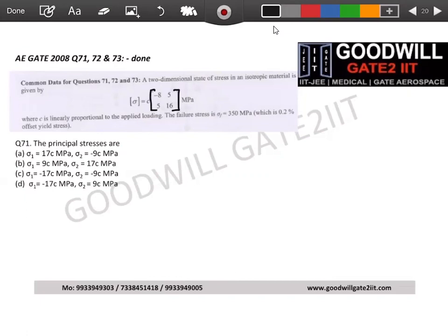If you have a stress matrix, its eigenvalues will be represented as principal stresses. So principal stresses of a stress matrix, if you use this application in maths, any matrix's eigenvalues are nothing but principal stresses in our case. What I'm trying to tell you is, in maths, you simply say you have a matrix, please calculate eigenvalues, fine. But now in structures, if that matrix is a stress matrix, its eigenvalues will represent principal stresses. Now, what do you mean by this? The property is this, guys, first property. And these are eigenvalue properties, not any structural property.